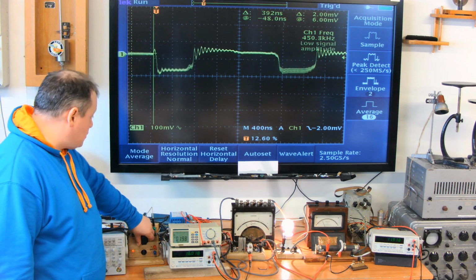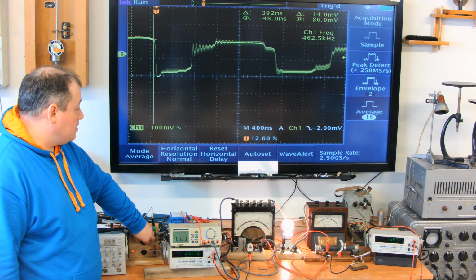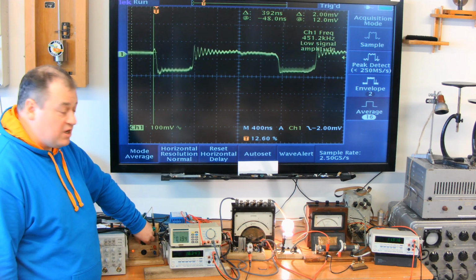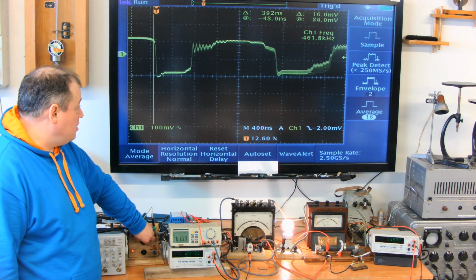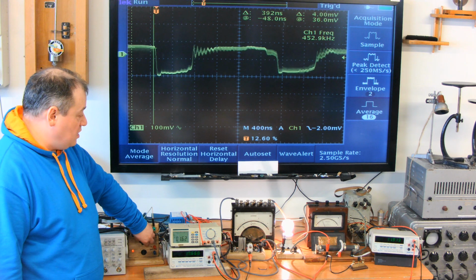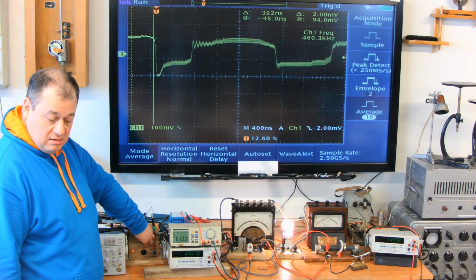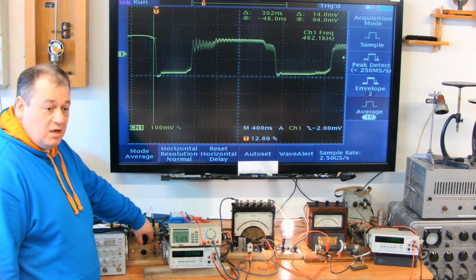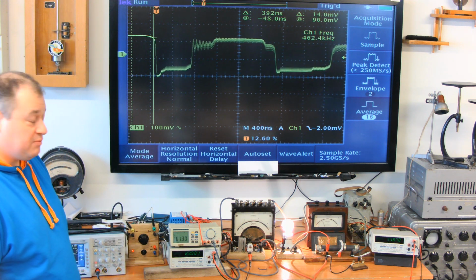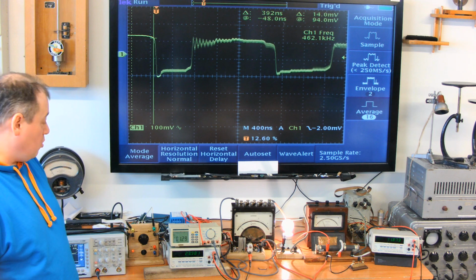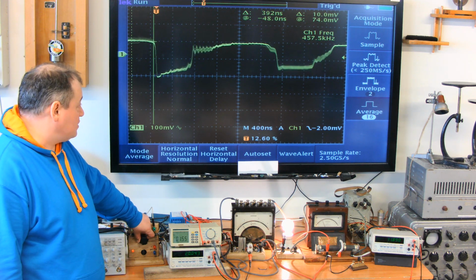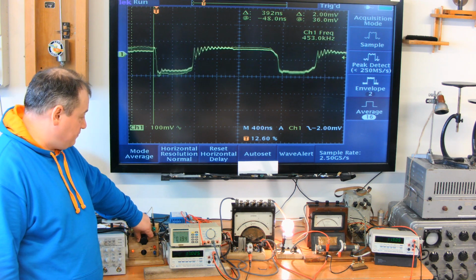The amount of energy supplied to the load remains the same. We see an inversion of Ohm's law because the characteristic of this network is defined not by its input resistance, but by the control law of the PWM controller, or control strategy, if you want.